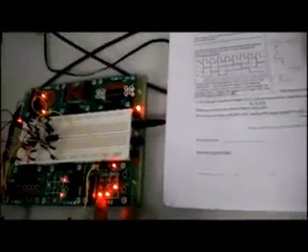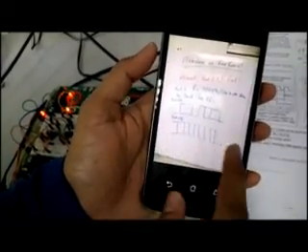Okay. So this is for part 2B. As you can see, we want to do the 7-bit LFSR. So this is our circuit. For part 2B, we still set the frequency to 500 kilohertz. So as you can see here, this is the result that we should see for part 2B.